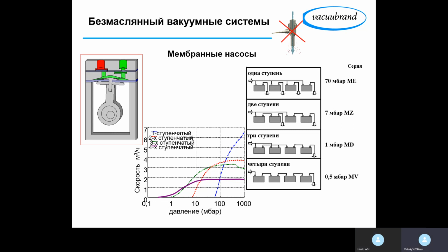Why? Because we have a leak rate. Main leaks occur in the seal that seals the vapor tube, but there are also other leaks that we can have in the system, like on the flanges or on the joints and so on. Okay, clear? Yes. Perfect.